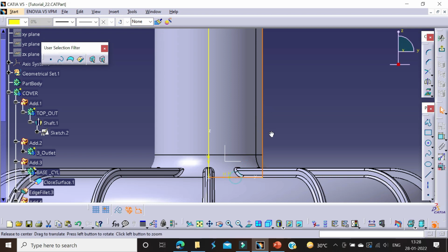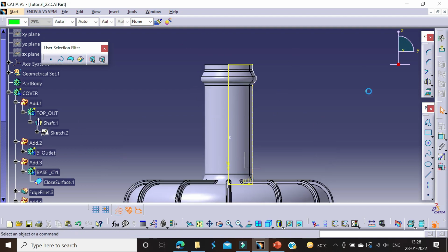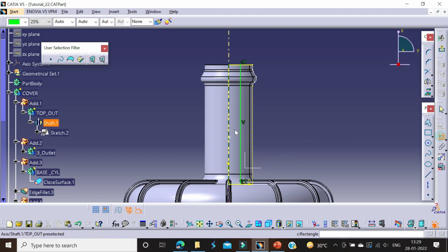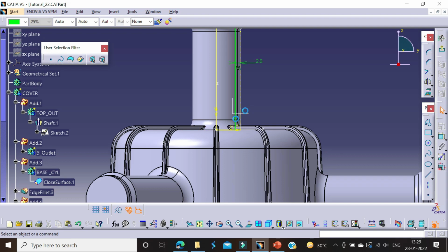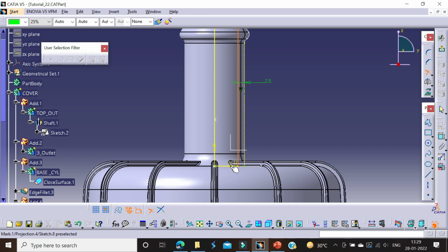If we take the reference of the three multi outlets we designed, there is a notch. That's why we are not using that minus thickness here. Instead, we are designing a separate removal body, or internal removal, for the multi outlets. So here the 2.5 mm wall thickness gets controlled.